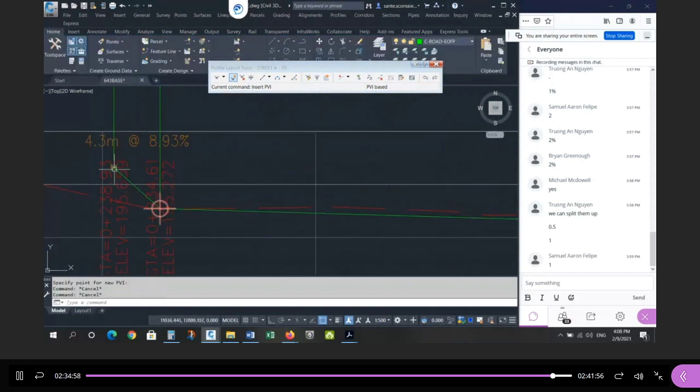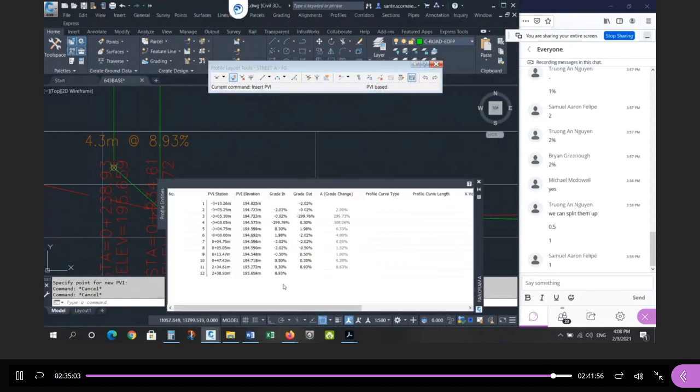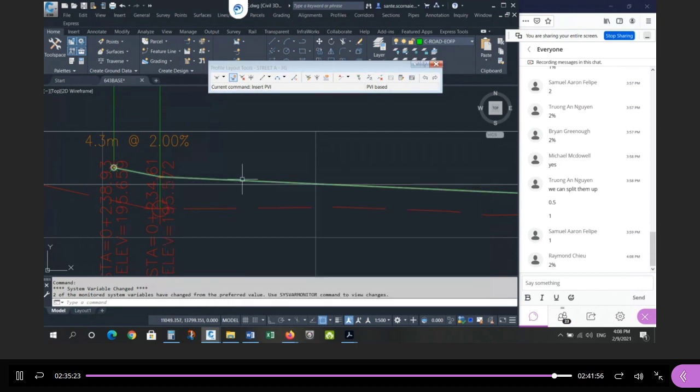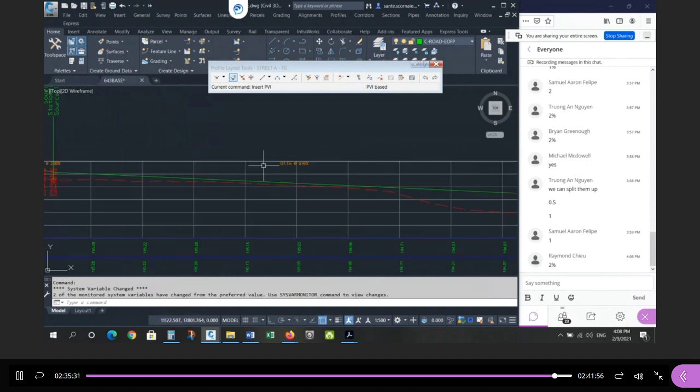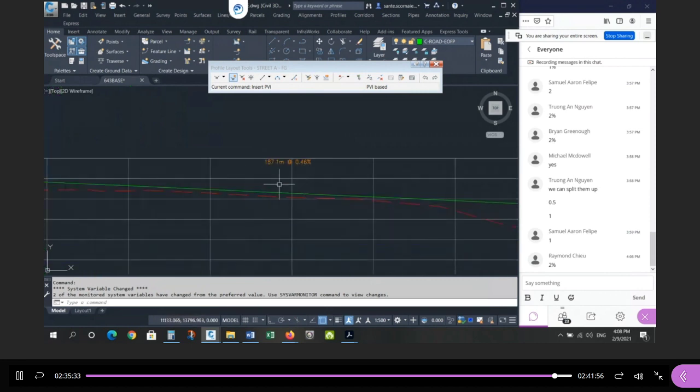All right, so what should the slope of this be? Now I'm working from the end, so I want to start here. What should the slope be? Remember, it's the pavement coming down from the crown, but working in the direction of increasing chainage. Positive 2%. Okay? So now you'll see this is 4.6%, right? It wants to be 0.5% minimum, right? 0.5% minimum.